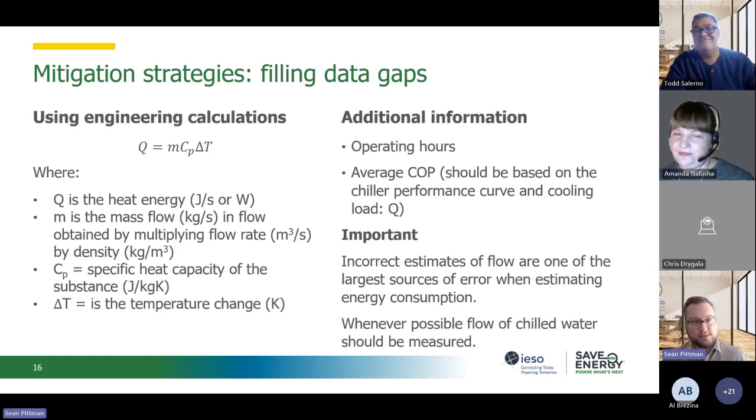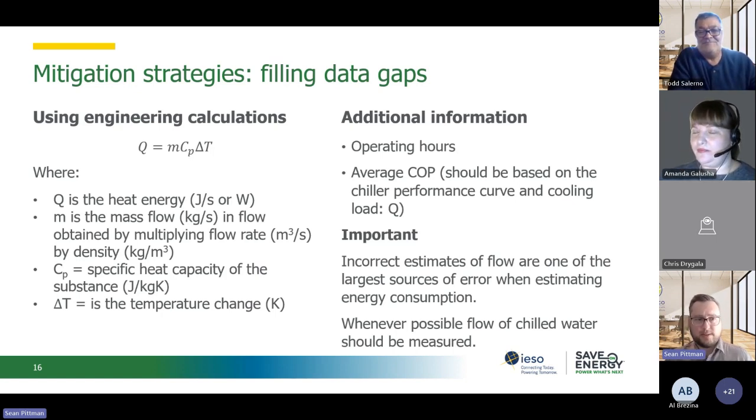Yeah, absolutely. I would also say, something to keep in mind, and it hasn't come up here, but I've seen it in many projects: we'll get information and somebody will say, here's the kilowatt usage of the chiller, but we don't really know where that data came from. They don't know what meter read it. They don't know what it was based on. It may be based on an amperage with a formula built into a BAS system. It may have a three-phase energy meter on the chiller. Not really sure, right? So it's good to know not only what information you have, but where it is coming from and what feeds into giving you that data, because there may be assumptions in the background. I'll touch on that again in a second. So how do we fill data gaps is a big piece, right?